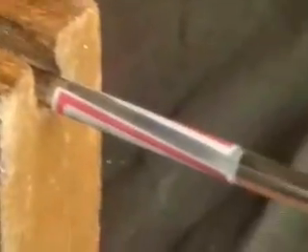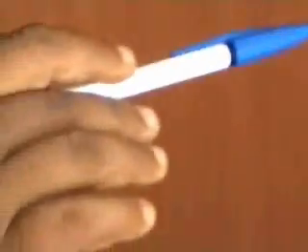Let us now see how to do the experiment. As I told you earlier, we need to pour water into the burette. Ensure the burette is also vertical and the capillary tube is horizontal, and the flow of the liquid is in drops, that is streamlined motion is there. So once the water comes to the 40 mark, you have to start the stop clock or the stopwatch. When it comes to 45, don't press stop, because we need time continuously at 40, 45, 50, 55, etc.